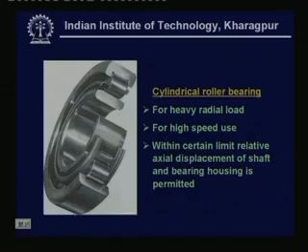So, you can see the roller bearings are normally used for heavier load, because a ball bearing has a point contact, and in the roller bearings we have a line contact. So, thereby the contact area, means contact location, is increased, and thereby it has a capacity of more load.